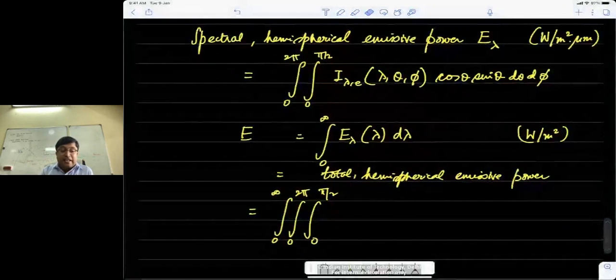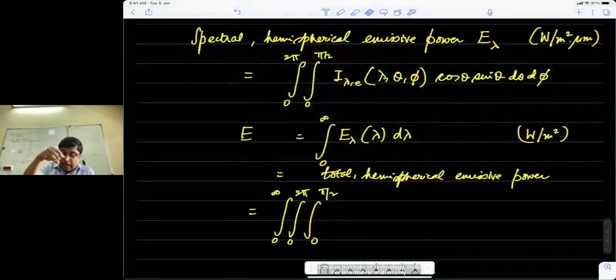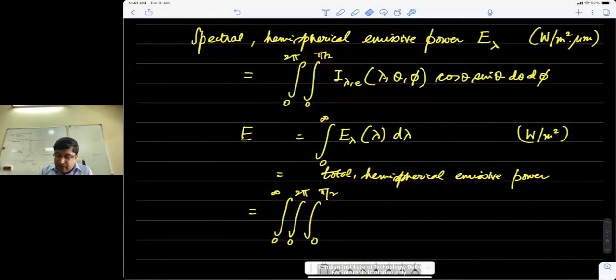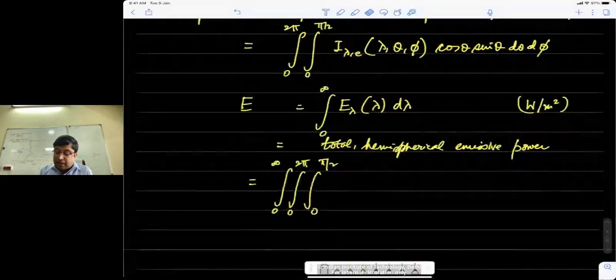If you know the amount of radiation emitted per unit area, we will only apply these things to simple geometries. For instance, a plane slab radiating: the same thing will happen at every given location. And even if it's a spherical or a cylindrical system, you know that the area element is the same everywhere. So multiplying by the total area is easy, and you get the actual power. But I don't have a great answer for why we still write power and have this watt per meter square. Historically it has just stuck and been carried over. There's no other answer for that.